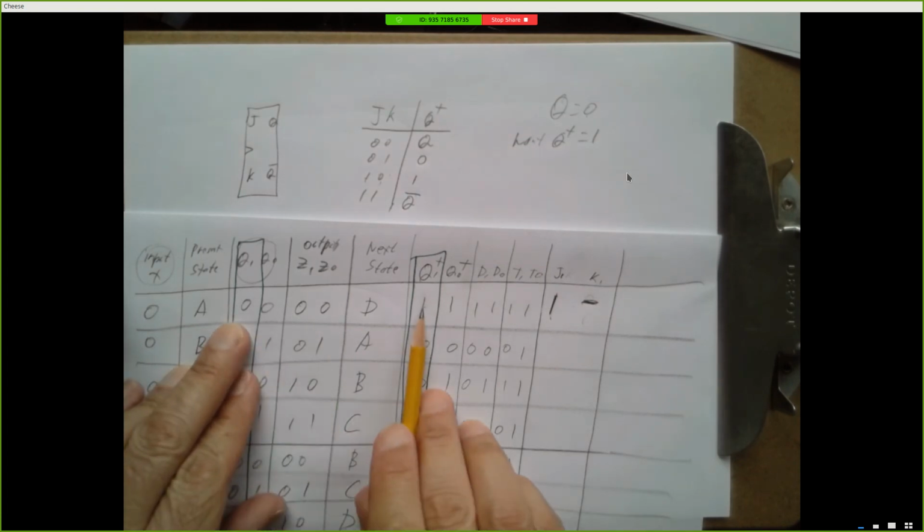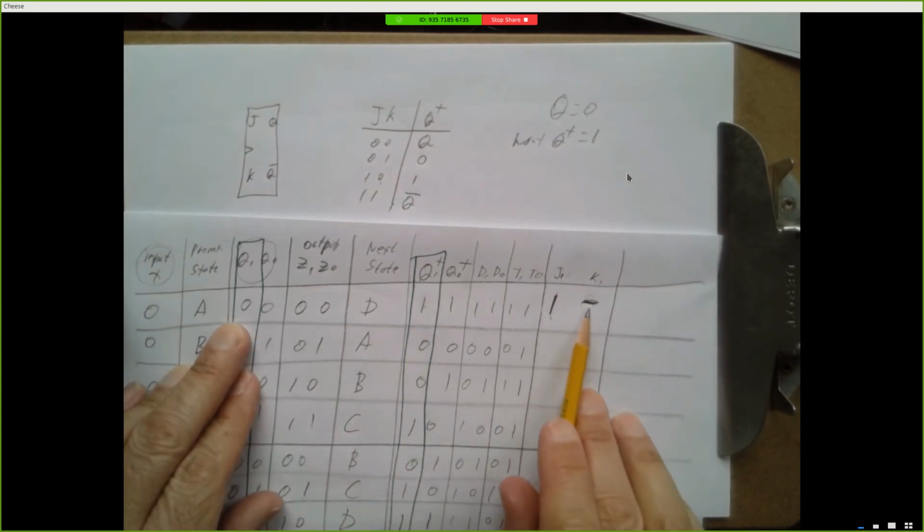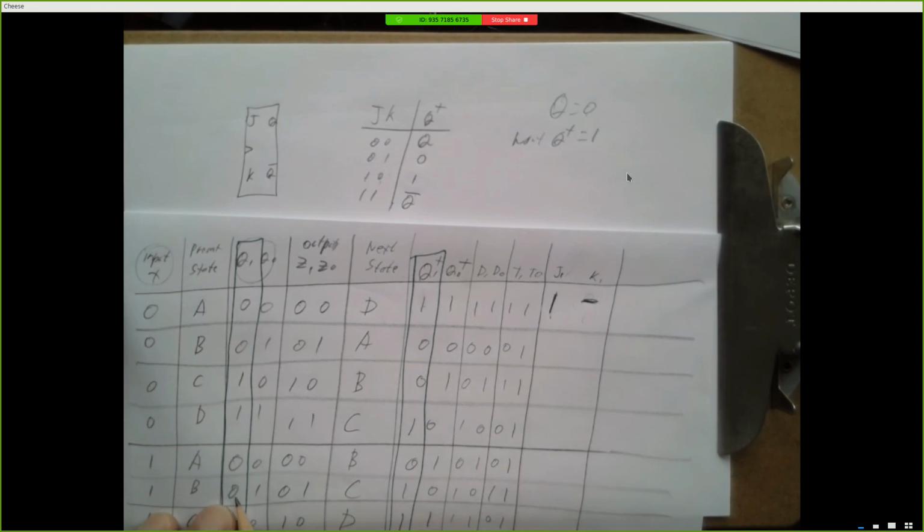And we really like don't cares in truth tables, right? Why? Because they give us dashes, and dashes you can choose to cover or not cover in your K-map. They never hurt you, but a lot of times they help you. So the more don't cares, the better. And any time that I'm going from a 0 to a 1, I'm going to say 1 dash. Okay, so here's a case where I've got a 0 and I want to go to a 1. That's going to be a 1 and a dash.